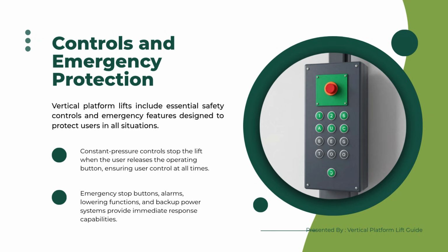An outdoor elevator can preserve the existing interior layout and may reduce disruption inside the building. This can be especially useful when interior shaft space is limited. Outdoor installations require additional planning for weather protection, drainage, corrosion resistance, shaft structure, and facade integration. For some existing buildings, an external steel or aluminum shaft can be a very practical solution.